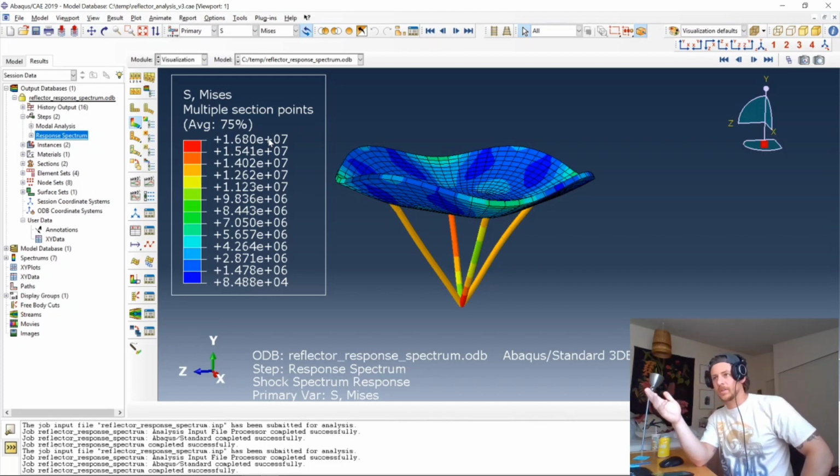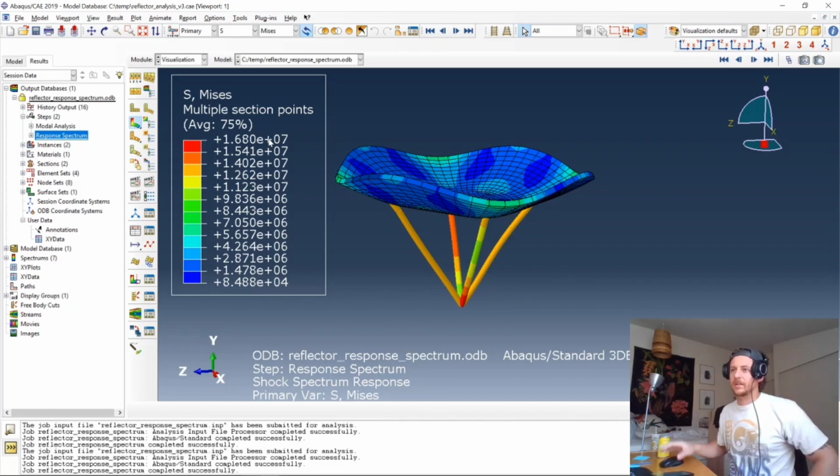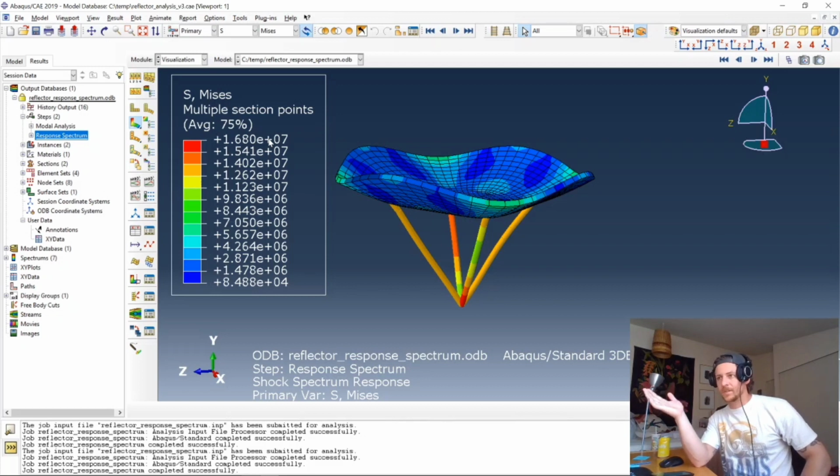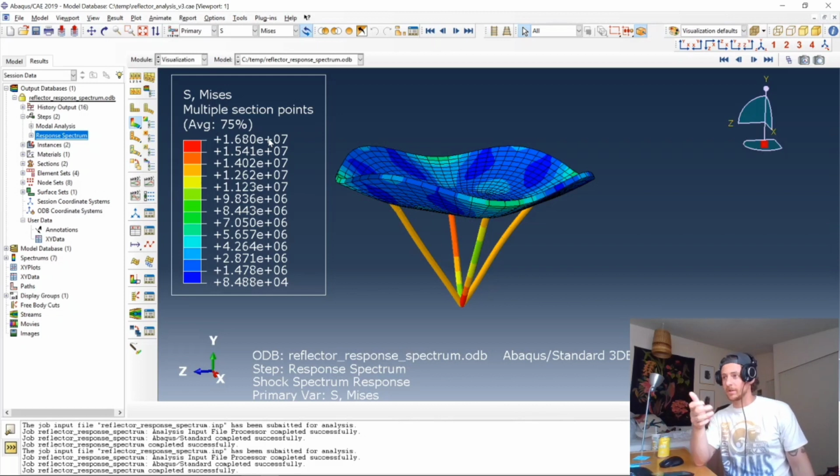That's well within the strength of steel. So if I were to look at this, I would say displacement was on the order almost of microns, and then stress, 10, 20 megapascals. So from a conservative, first order sense, I would say this design is probably okay, thumbs up.